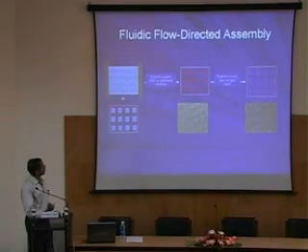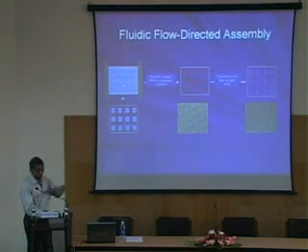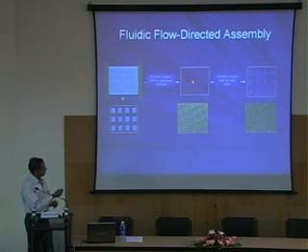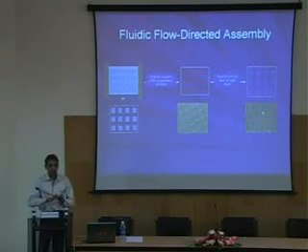Once you have these aligned nanowires on top of a layer of material, it could be a plastic material, you can transfer them onto your substrate, change the direction of the substrate and grow the nanowires in the opposite direction, so that you can have crossed arrays of these nanowires.